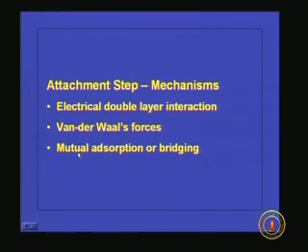So, we have seen that the filtration mechanism can basically be classified into two groups, transport mechanism and attachment mechanism, and the attachment mechanism is almost similar to that of coagulation. So, in filtration also, if we add coagulants and destabilize the particles, the removal will be much easier compared to colloidal particles which are not destabilized. This is true when we talk about the rapid sand filter, which is a depth filter.